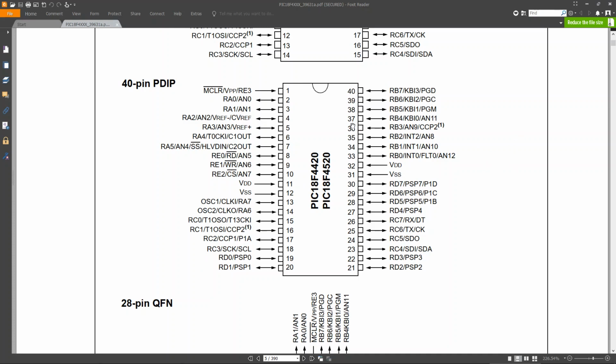For LCD, it's advisable to pick pins that are confined to the same region. Like here, if you want to use the LCD in the 4-bit mode, you can just select pins RB7 to RB4 for the data pins, then maybe RB0 and RB1 for the register select and the enable pin. This will make a less complicated design.